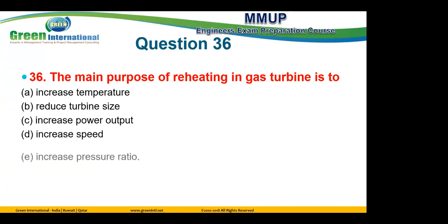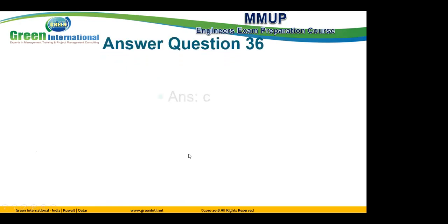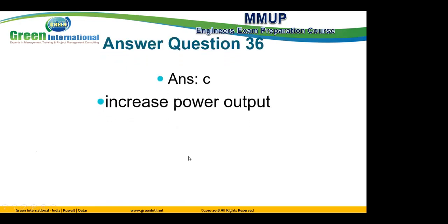The main purpose of reheating in a gas turbine, be careful, because it says main purpose. Increase speed, increase pressure ratio? No, actually the main purpose is to increase power output.